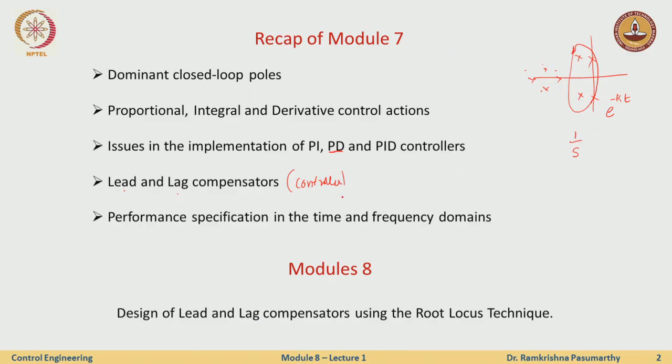And okay, so given a system, how is the performance criterion specified? It's usually specified in terms of some kind of peak overshoot, some kind of settling time, and so on. And these loosely translate, we know the formulas, into specifications of zeta and omega n, and I can construct the dominant poles based on this, right?